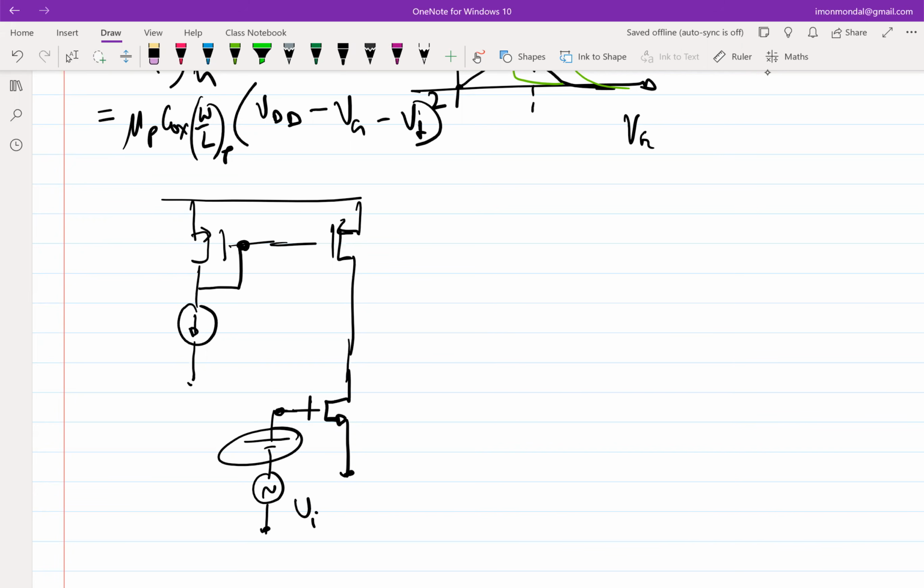So what you can also do, and what is often done, it's not necessary to connect these two directly. You can connect these through a resistor. Let me call it R infinity in this case, M1, M3, M5. Let's say this is R3. And then what I can do is couple this VI, AC couple it through a capacitor, CC.